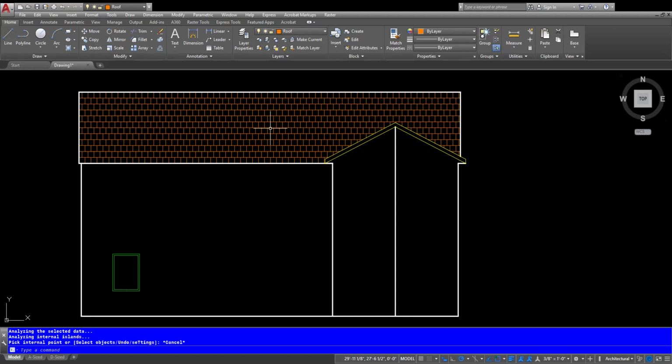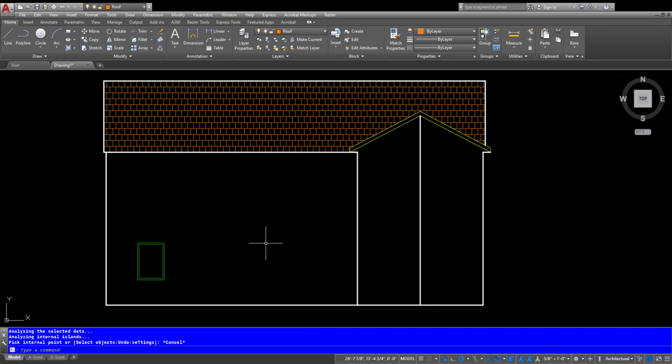Okay, so we've got that right now. The next thing is I'll put in the siding hatching. The siding hatching allows us to also put this in here. Oh, and by the way, your hatching is intelligent, so it can miss your dimensions. If you have some dimensions and they actually need to have the hatch go around them, just leave them turned on and it'll hatch around them.